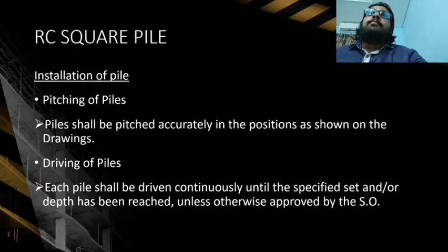The first one, pitching of pile. Piles should be pitched accurately in the position as shown on the drawing. Next, driving of pile. Each pile should be driven continuously until the specified set and or depth have been reached, unless otherwise approved by the SO.